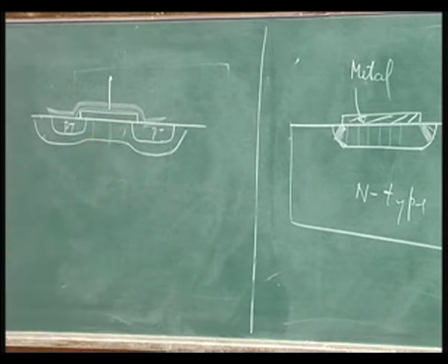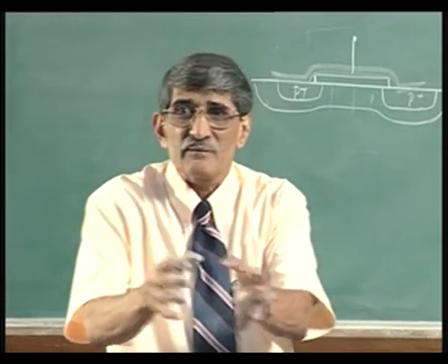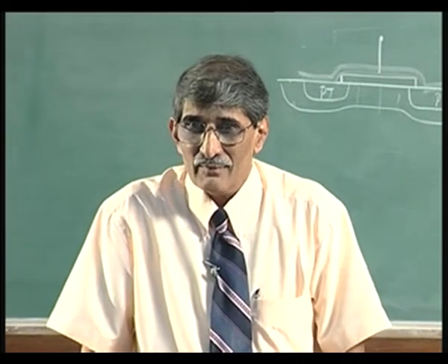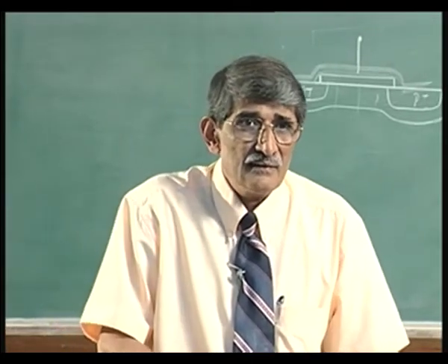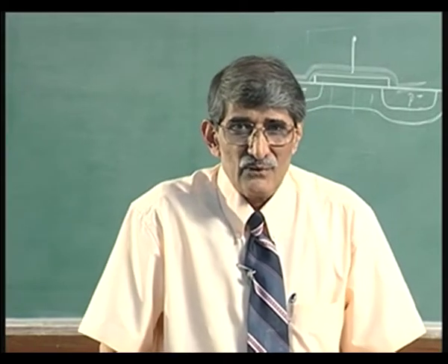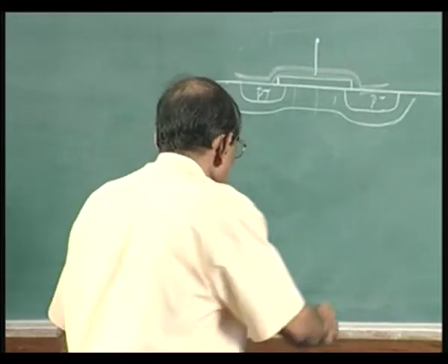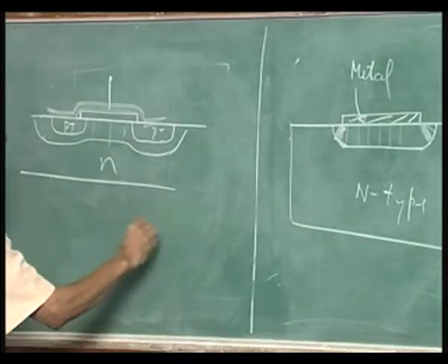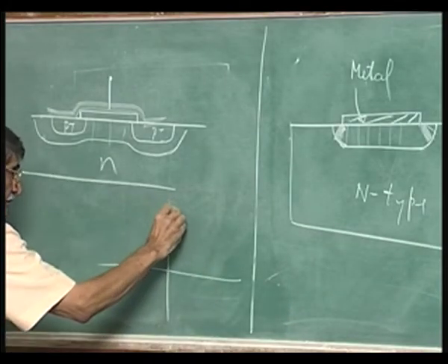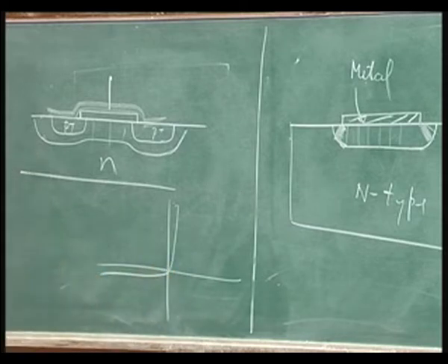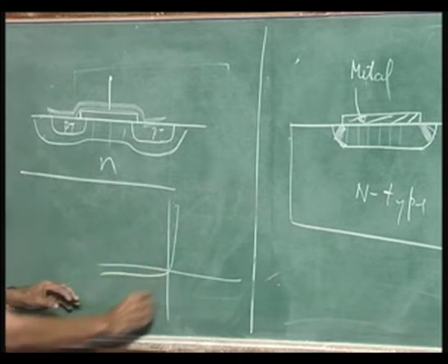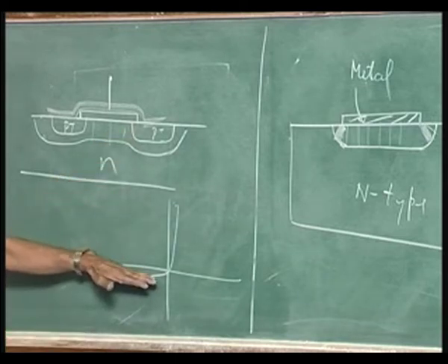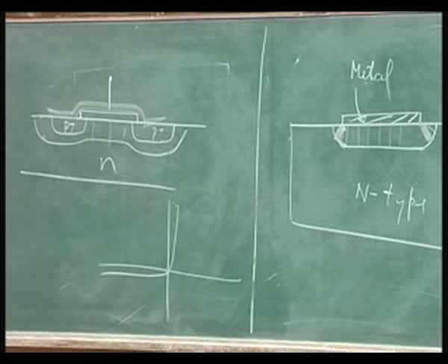So, what you have done is shifted the crowding effect from the Schottky to the p-n junction, and the current in the p-n junction, even when its peak field is higher, is much lower than that of Schottky. So, when you do that, you get characteristics which are close to ideal flat. We have seen this. This is the hard truth about this: the leakage has shifted up there.